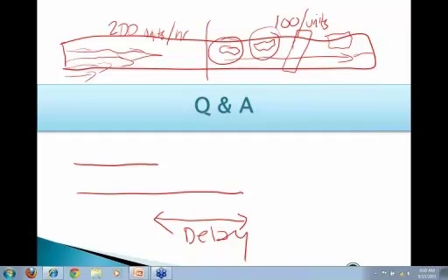If you have 3, 6, 9 weeks in your contract for the contractor to prepare their schedule, you can say each one of those weeks we're going to meet, we'll bring a projector, we're going to put that schedule up on the board, and let's just talk about the schedule. And you'll begin to see right away how that contractor's doing, and you can actually get involved and put your input in the schedule before it's ever submitted. That does a couple things. You can help see where the schedule's at before it's submitted. It helps the review process, all that kind of stuff. And that's probably one of the best things I know to help get that quality that you can't enforce in the scheduling specifications. Okay?